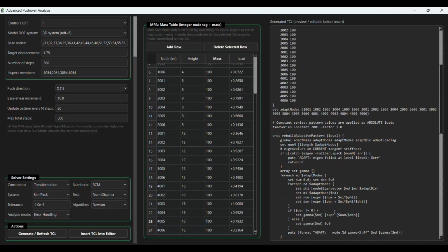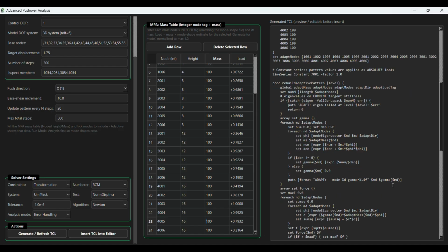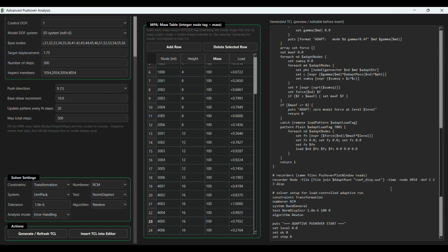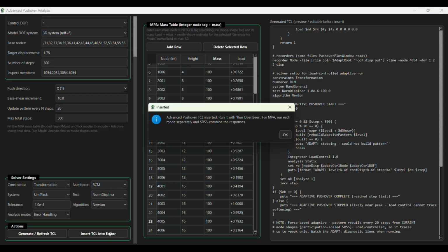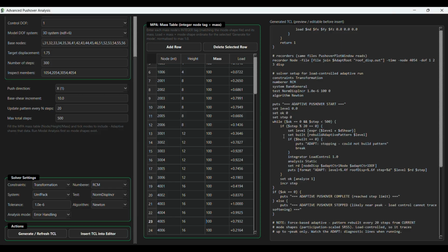The analysis is expected to stop converging near the peak. If that happens, that's the method working as intended, not failing. Error handling mode in the solver settings is worth enabling here specifically, so the run degrades gracefully into that expected non-convergence rather than halting abruptly.